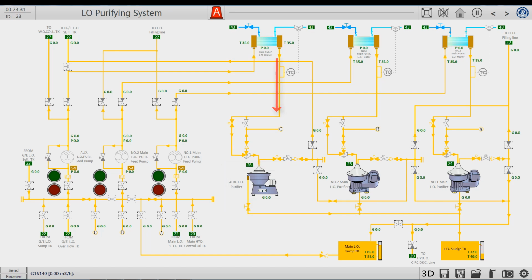The line passing through the heater is the oil inlet line of the oil separator. This is a solenoid 3-way valve that controls the oil intake. The other side of the 3-way valve is the bypass pipeline. The throttle valve also has a bypass function. When the lubricating oil pressure into the oil separator is too high, it bypasses directly through the throttle valve, and the bypassed lubricating oil returns to the suction port of the oil supply pump. The 2C mark shows the connection of the pipeline.